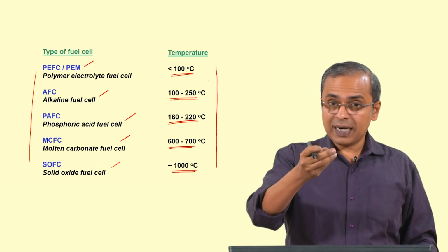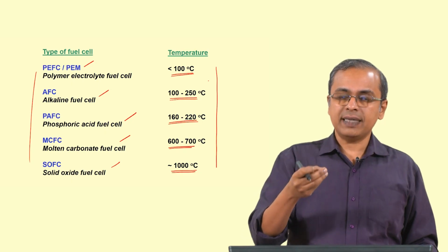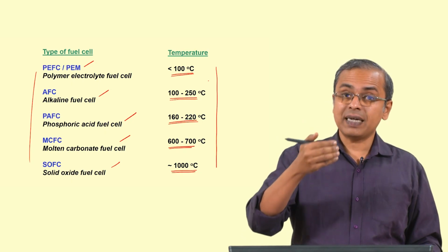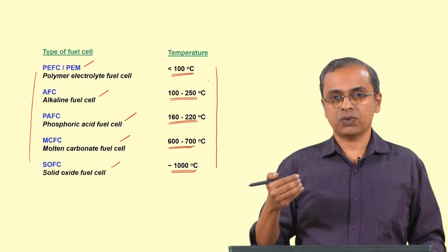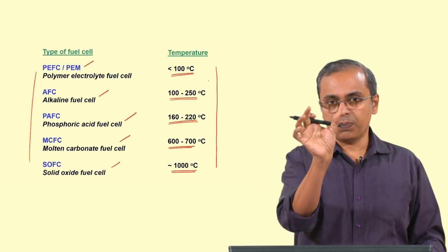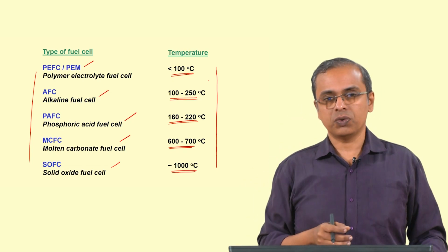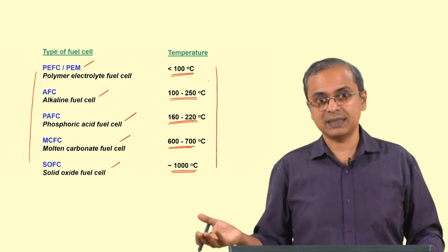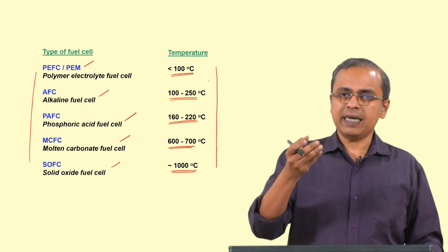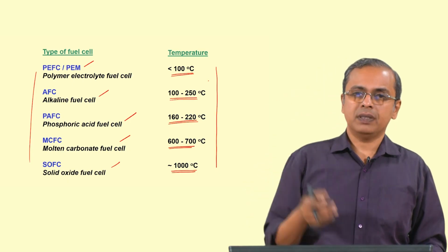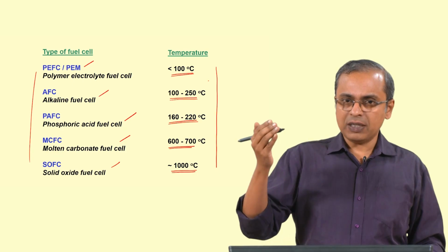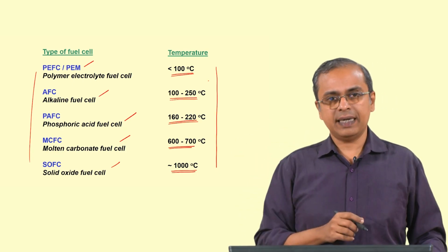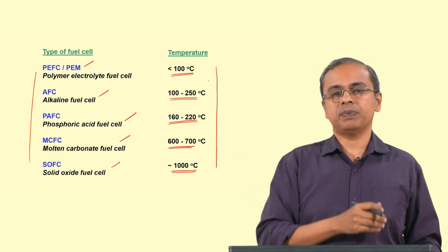Now when you draw current from the circuit, that is effectively the rate at which you are drawing electrons from the circuit. Okay, so you have some load, you are putting some load there, and let us say it is a 5 amp circuit or something like that. Let us say we usually do not draw 5 amps, even though it is a 5 amp circuit, we are drawing much less than that. So in any case, let us assume you are drawing half an amp. So in half an amp you can actually calculate how many coulombs per second it is, and therefore how many electrons per second it is.